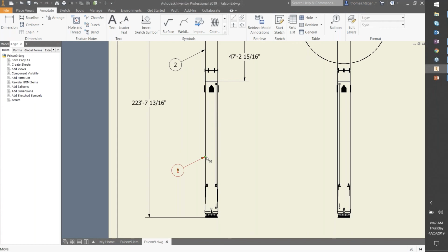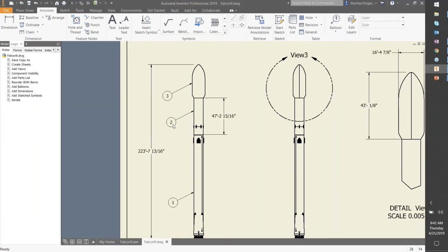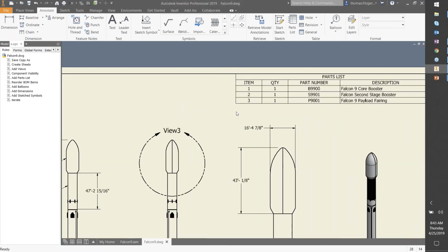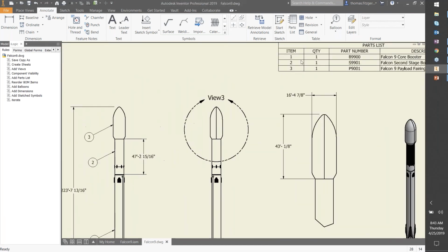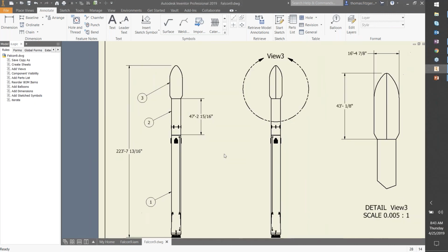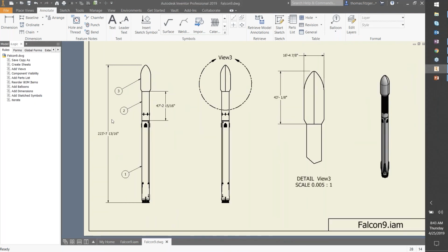And then I'm just using the normal Inventor behavior to fill in the item number relative to the item number here in my parts list. So I'm not doing anything special there. I'm letting Inventor manage that automatically. I'm just pointing out where the balloon should be and where the attachment point should be. Because if I move this attachment point to something else, that item number automatically updates. So I don't need to worry about providing that. I just need to provide the geometry, and then Inventor takes care of everything for me, okay? So that's balloons. The last one here, dimensions.